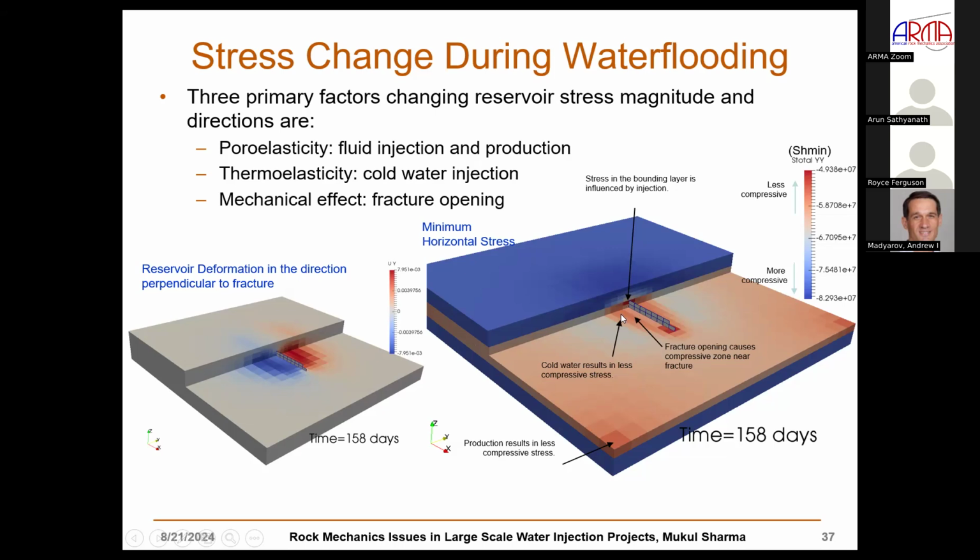And the usual way of doing that is to say, okay, you have a stress profile and the containment is controlled by that. The question that came up here, which was unusual, was how big a role does thermal conduction play in the containment of this fracture? In other words, I'm cooling down this portion of the rock, and when you cool this down, what is going to happen to the stresses in the shale above because of conduction? And it turns out that